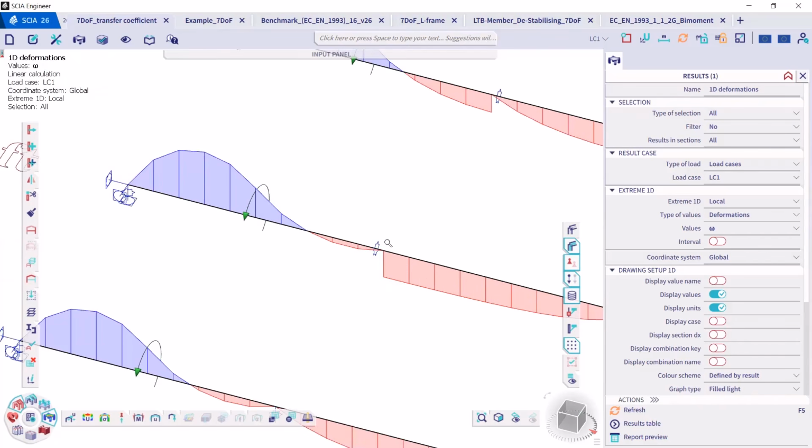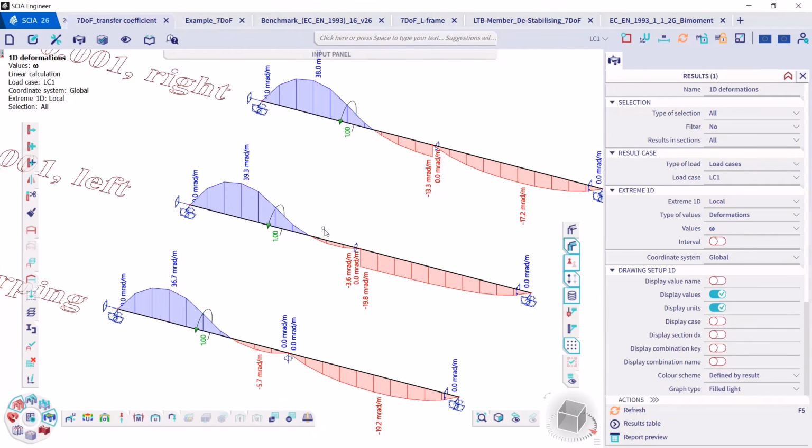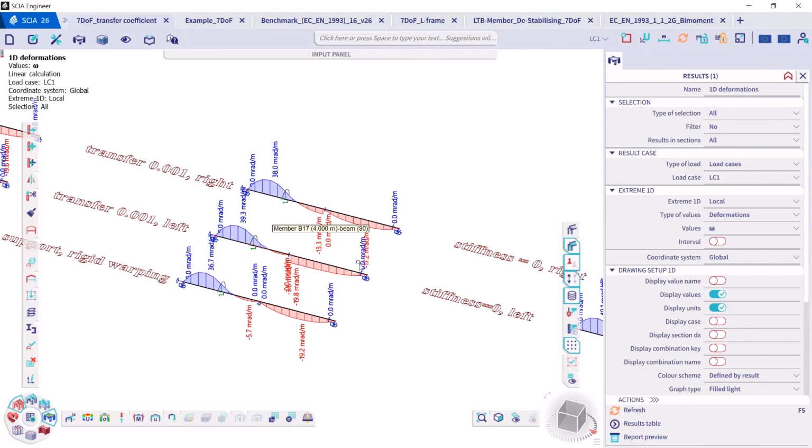It is not recommended to put the hinge on both sides. This is why for now I have always shown the hinge being placed on only one side, because it can cause some issues in the solver. So either you put it on one of the two sides or you can also use supports as in here to simulate your boundary conditions.